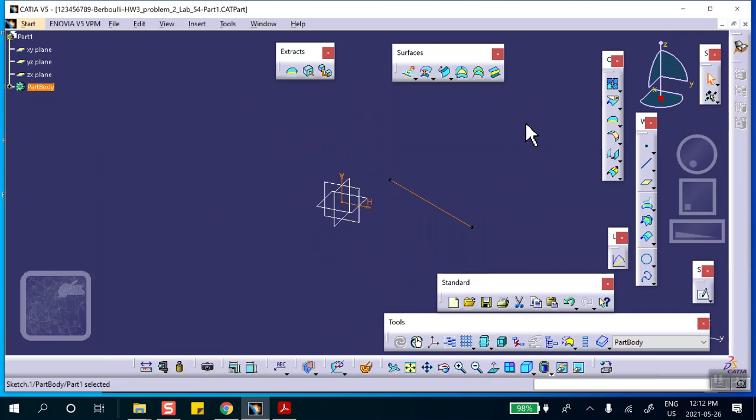Now I'm going to take this thing and exit the sketch first. And then I'm going to shaft it. This is extrude, and I don't want to extrude it. Look for shaft. You'll find it. I don't see it here. CATIA actually calls this thing revolve. Let's see if we can find it. If not, then I might have closed it because I didn't think I was going to use it, so let me remind you how to reset your toolbar.